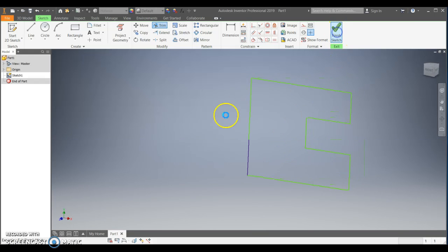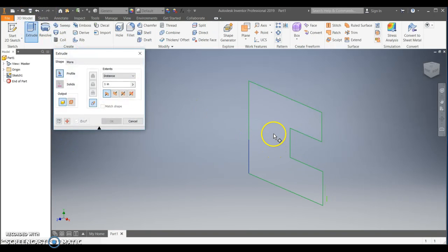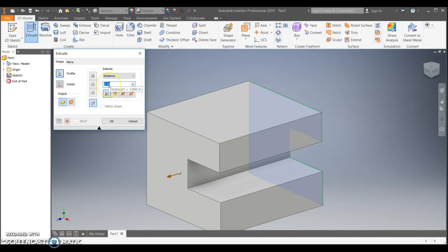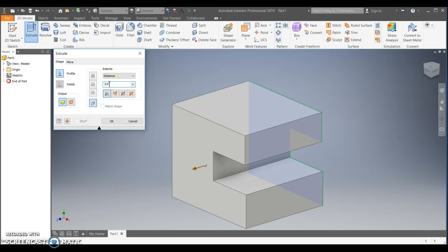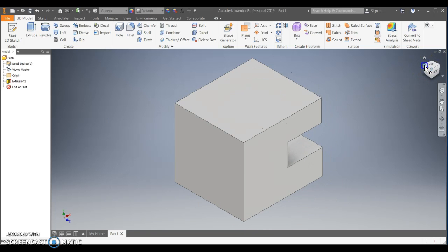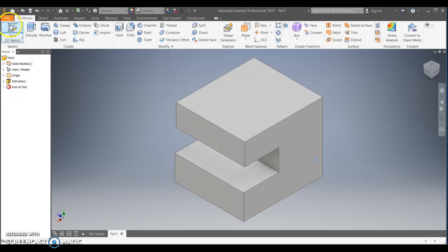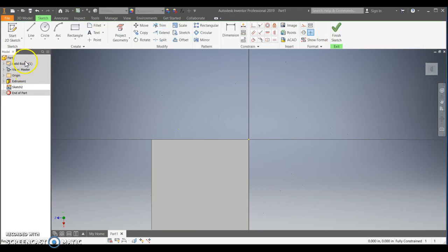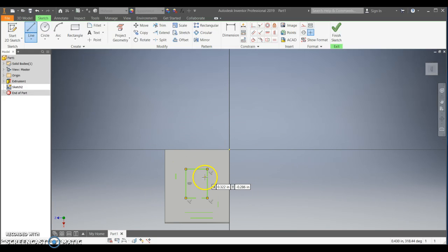And so once you are done with that view, you should be able to select and create that block-like object. So again, you can use the rectangle tool, or you can use the line tool. Now with the line tool, the two things you need to be conscious of most of the time, actually with any tool, but particularly with the line tool, is what exactly is the size of the line that I'm trying to create, as well as, and if you notice, what's the degree of the line that I'm trying to create.